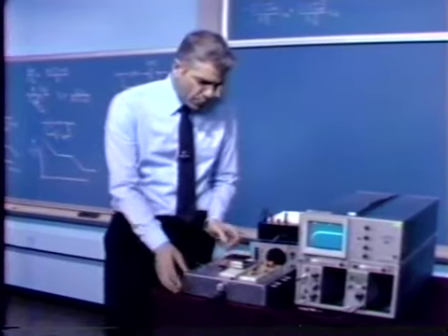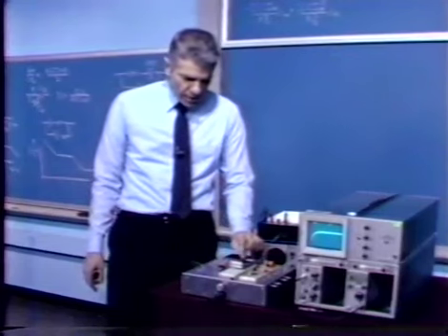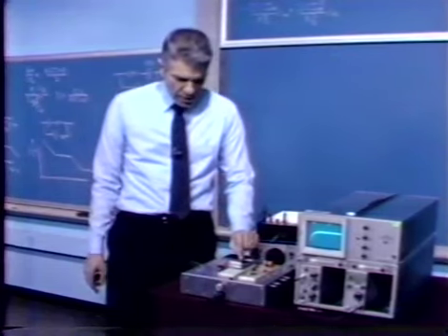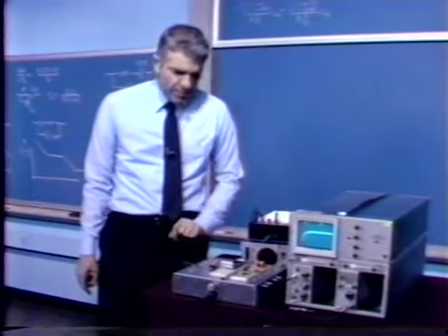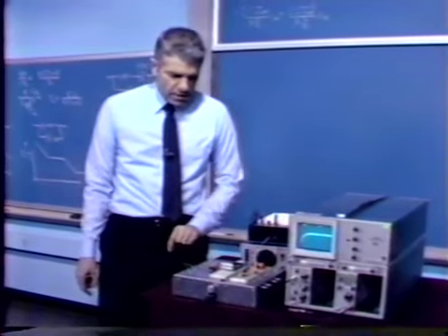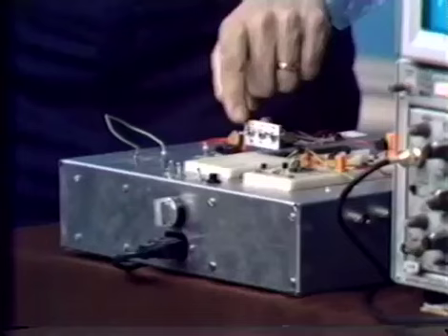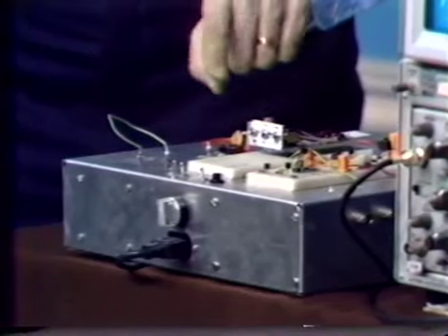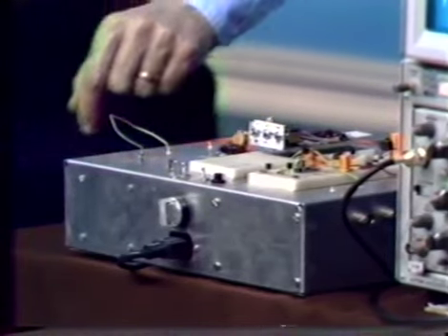We've changed the board in this case. Here's the circuit itself. We have the 301A or the 101A type amplifier and its buffer amplifier, and a series of switches on the front that first of all let us select from various types of compensation, also let us select the R1, C1 product. So that's what these three switches do.